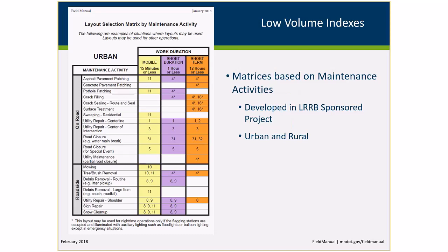In the full MUTCD, there's a Part 5 section that talks about low-volume roads, and within it, it talks about how you can reduce the number of devices in the appropriate applications if you've got low volumes, especially if you've got low-speed roads. So this new section on low-volume roads has elements where you can have fewer devices out there in the right applications, and I'll talk about some of them as we go through here.